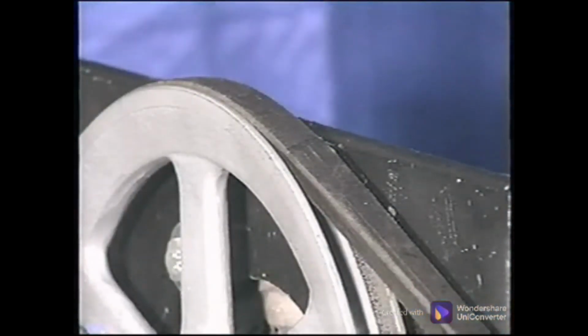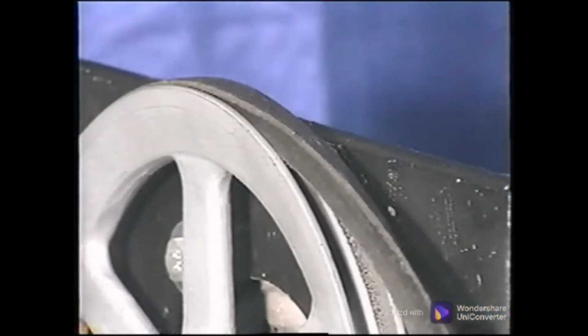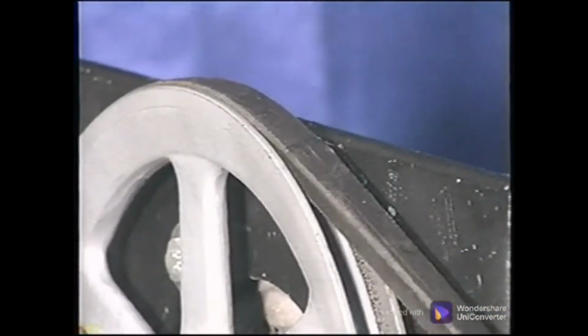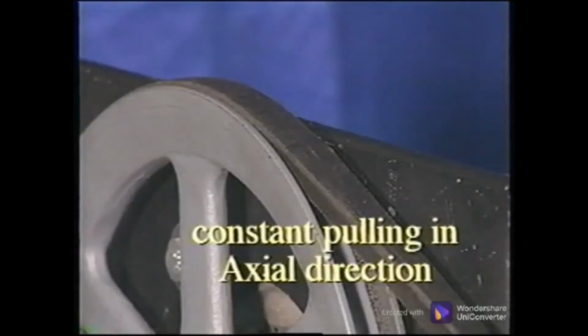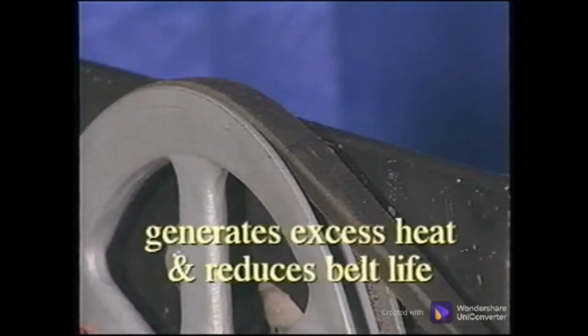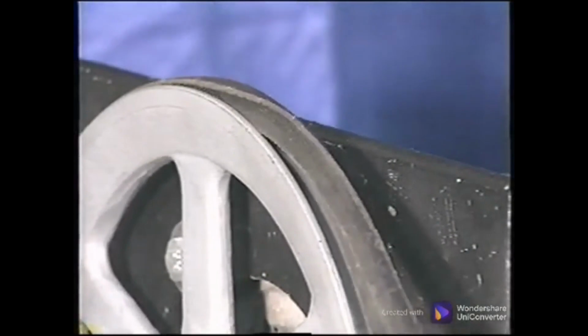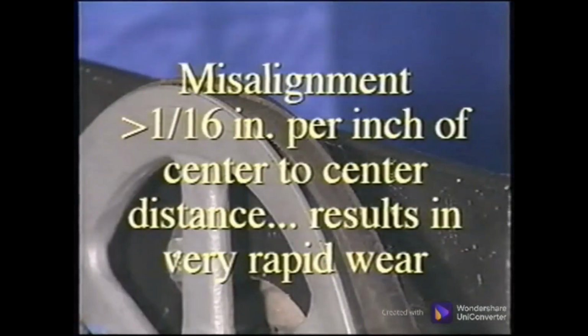With any type of misalignment, the belts ride up on the groove wall and slap back into the groove, repeating a cycle of riding up and slapping back into the sheave once during each shaft rotation. This produces a constant pulling against the side of the sheave, which is along the axis of the shaft. The rubbing and pulling against the sheave generates excess heat and wears both the belt and the sheave, drastically reducing belt life. In extreme misalignment, a belt may roll over in the sheave or actually ride out of the sheave. If misalignment is greater than 1/16 of an inch for each inch of center-to-center distance, very rapid wear will result.